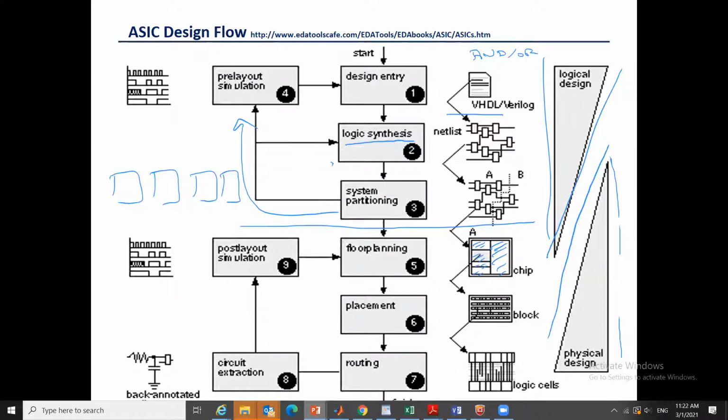This is also where a lot of people now are trying to apply machine learning to the EDA problems. And now within these blocks or units, I'm also going to design them so that they are optimally placed. And then I'm going to design each cell within these blocks. So I have a library of cells that get built and developed, and then the floor planning takes care of the big unit picture. This will result eventually in extracting the parasitics, which we will talk about a bit later.